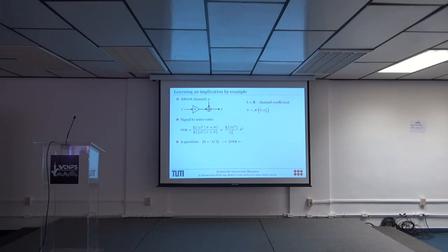Well, the standard answer is, it will go down by a factor of 4 because we have that square here. Well, this is only true if the variance and the channel coefficient are independent. And it's not clear that they are really independent. There may very well be situations where they are heavily dependent. And therefore, we have to figure out how the noise comes into the system, how it interacts with the system, and we will do that, again, with a simple example.